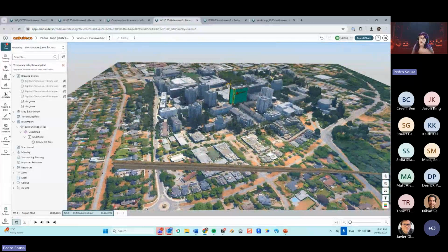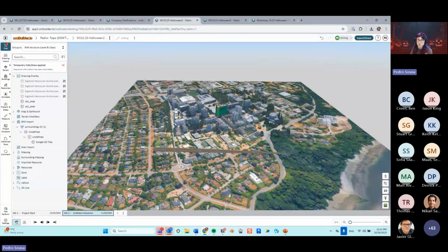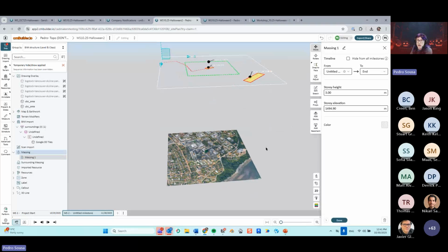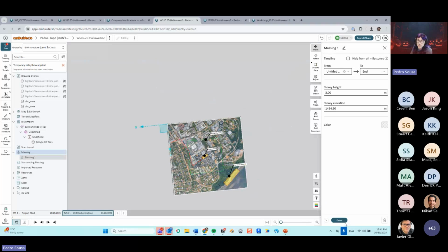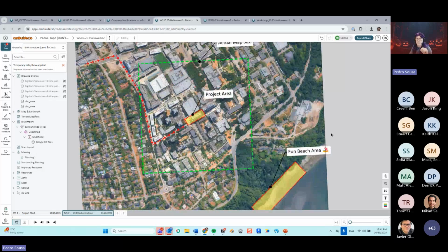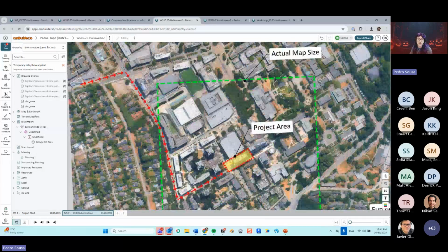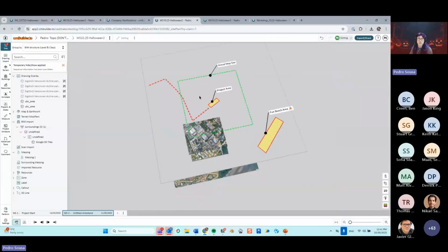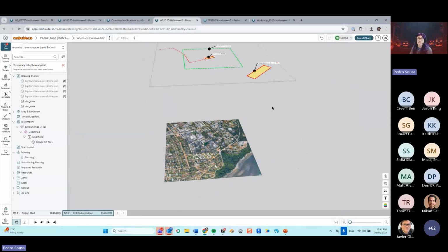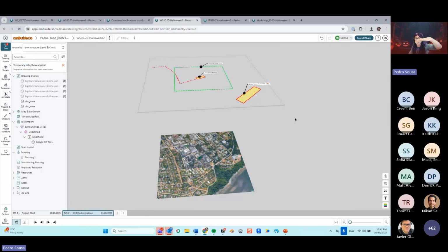And if you combine this with the instructions I mentioned in the previous workshop for the 2D layout plan, we can also put a massing on top. Then when you look from a 2D view, you get the massing where you can place elements, like these annotations, all these arrows, the lines, the callouts and the zones, all placed on the massing because I want to use that massing as a layer to host my annotations.